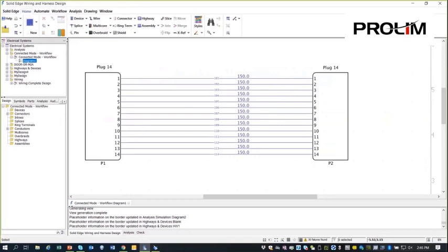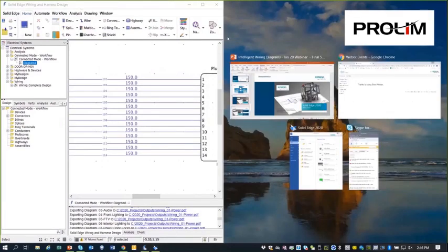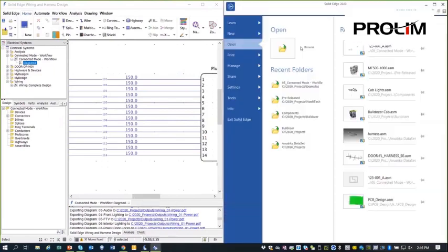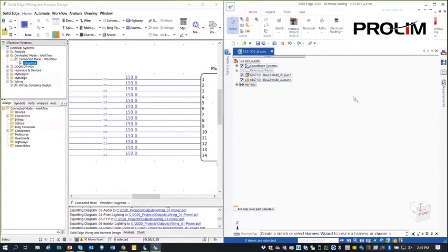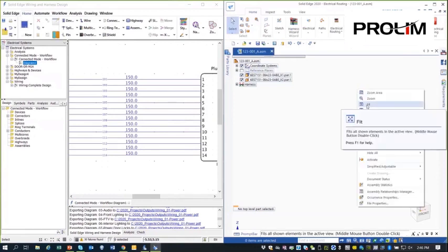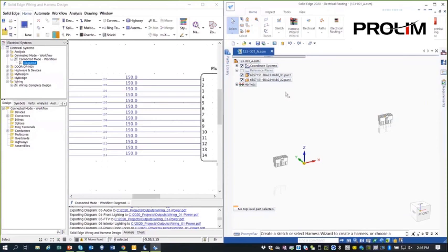So I'm going to move this to the split screen, and I'm going to bring up the Solid Edge environment. And I'm going to bring up an assembly in Solid Edge that has these 2 connectors placed into the assembly. So the idea is, rather than having to, in MCAD, redraw those wires, put in those properties in the details, we want to read the information from our electrical systems team. So the way we establish this connection is under the electrical mode here. Pull down, I say connect.